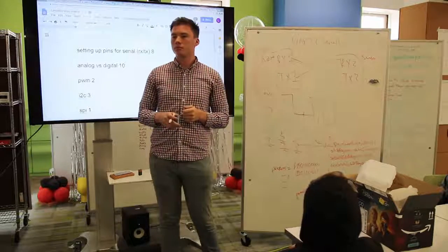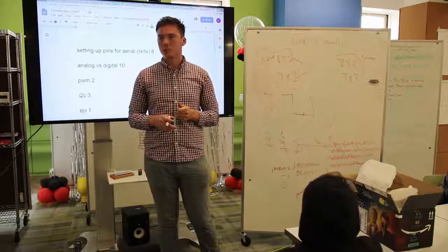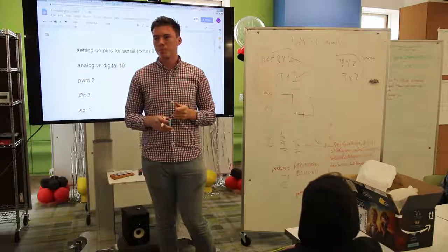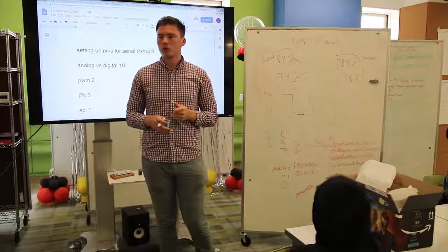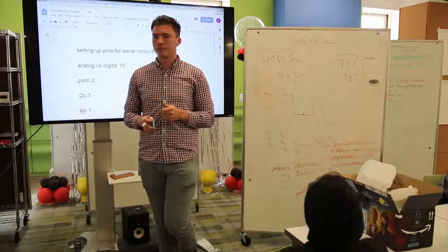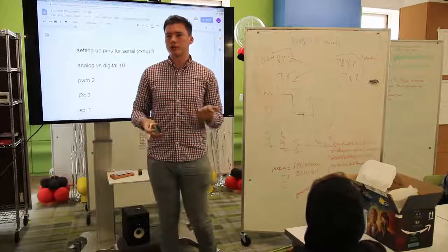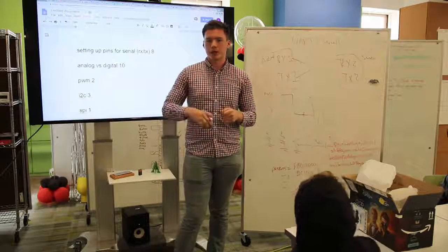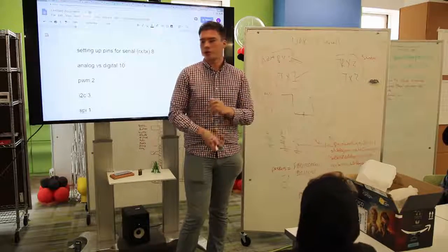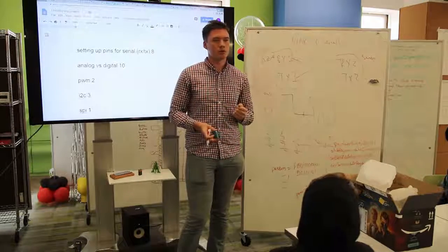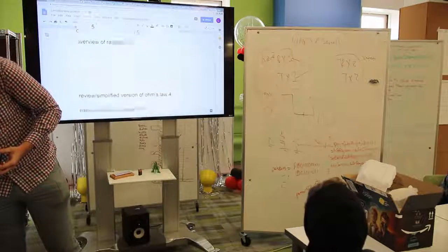And if you wanted, are you allowed to redefine, because RX and TX are kind of keywords on the pin? Is there a way that you can redefine the 0 and 1 pin so that it will fit what you want to do? Because if you're using RX and TX for pins 5 and 6, and you change 0 and 1 to a normal pin. Just like a normal digital I/O? Yeah. There's no reason why not. They're just, if you want to, you can hardwire them to that special hardware. Cool. Some really good questions. Anything else, guys?